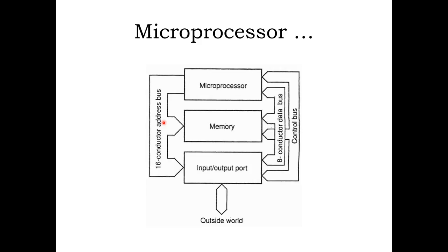And that's why everybody is running after the new 64-bit architecture, where you can have more memory locations, because every location needs an address and an address is a number. If I give you a 4-bit microprocessor, then your memory will have only 16 locations, because every location needs an address, a unique number, and you just have 16 numbers. You cannot write anything more than 16. Do you see the problem?